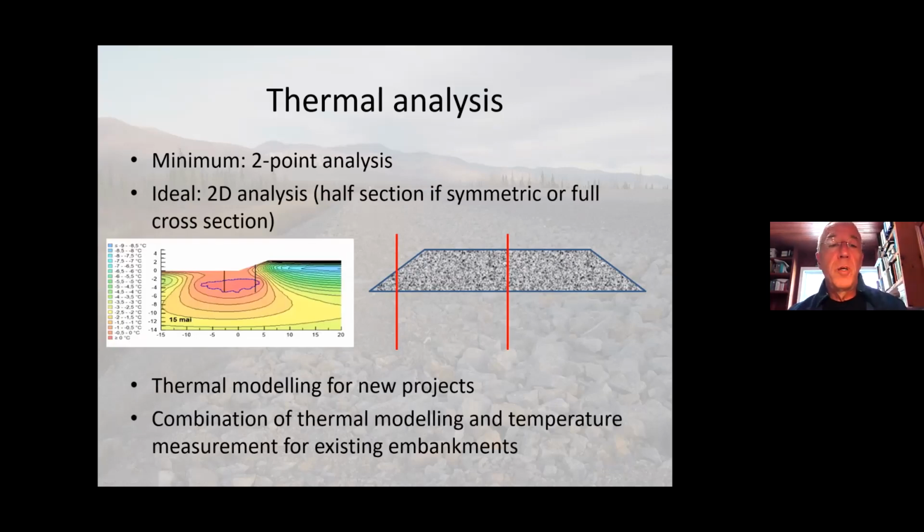For new project, thermal modeling is a very good way to assess the problem. Because of course you don't have any information on the behavior of the embankment since it's not built, so you have to assume a few design things, and then do the modeling of the thermal performance of the embankment based on your knowledge of the site.